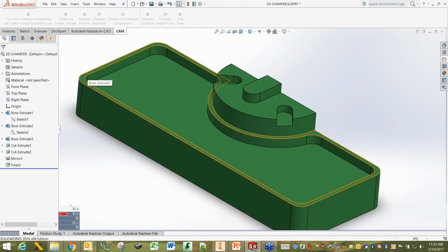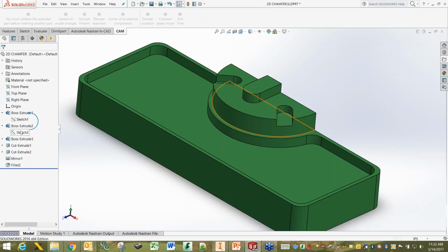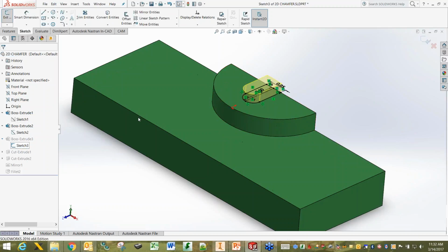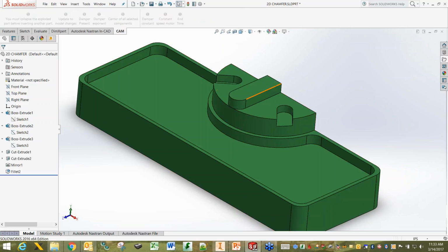And update that. This boss here, this sketch, there's another one. Yeah, this guy here, this needs to change. Maybe we should make that 1 inch or maybe 0.75. That looks pretty good. So we've made a couple changes to this part. We've extended the boss, and we've made the part very big. Okay, so the engineering change has taken place.